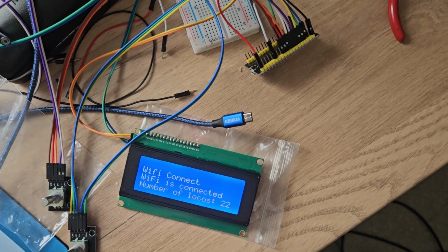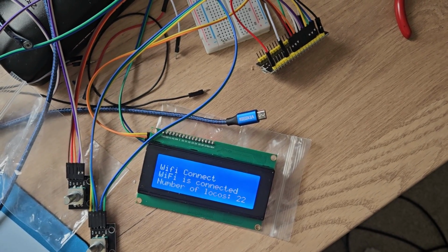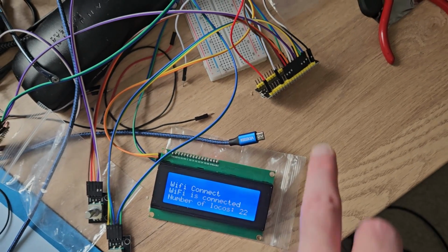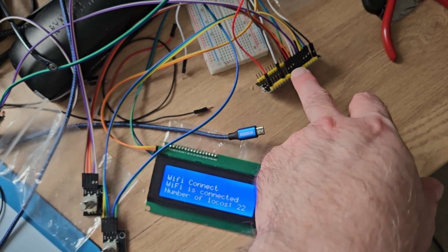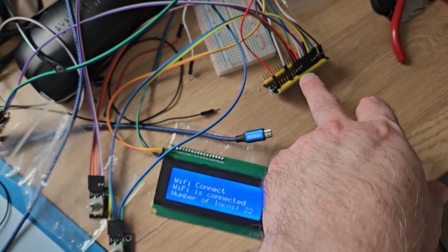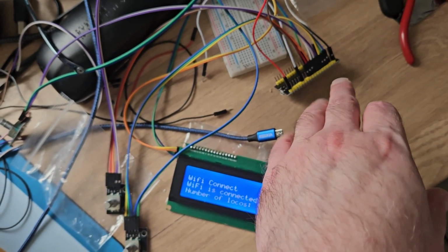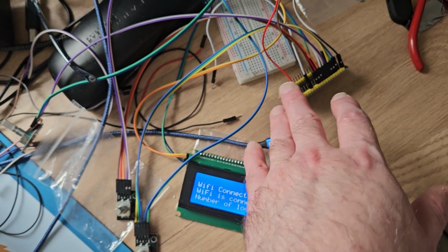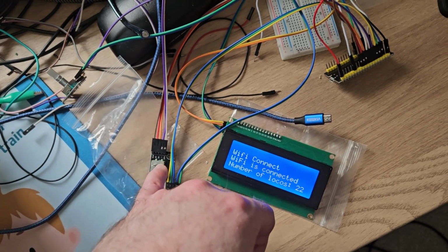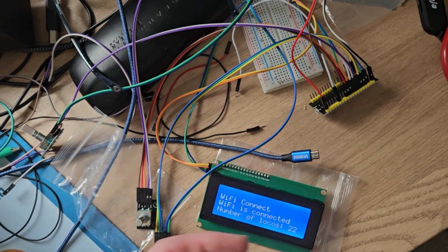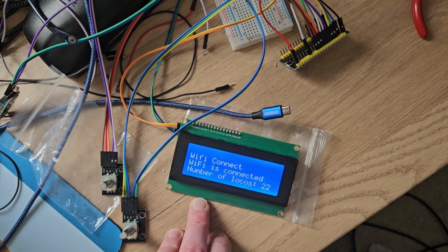And the first thing I need to think about, if I'm going to build this thing into a second box, is power. How I'm going to power it, because I don't want the ESP to be tethered to the PC all the time through a USB cable, so it's got to have independent power. And with the first box, all I really did was, if it had its 5 volts of power, it was fine powering the 7 knobs. It could get away with that with its 3.3 volts, but it can't power a screen as well.